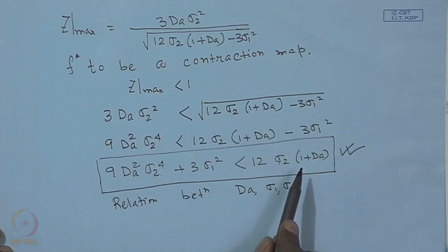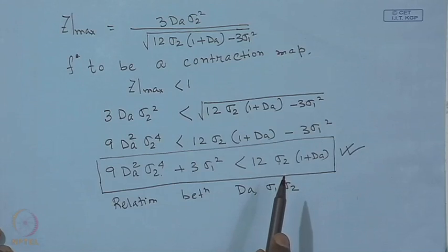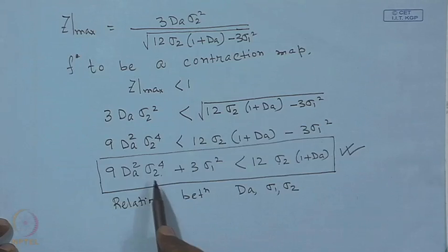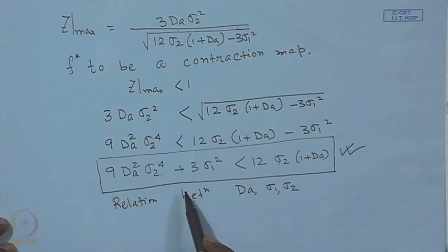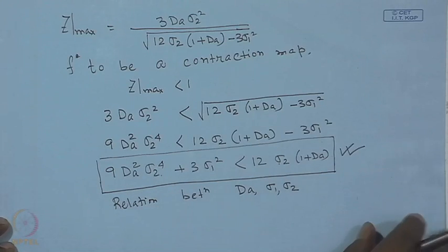So, you have to select Q and Cf, these are the actual operating conditions you are controlling as an operator. On the other hand, these kinetic parameters K1, K2 and K3 are fixed by the rate expression, you do not have much control over them. The control you have is over the feed concentration and volumetric flow rate, and these non-dimensional numbers are combinations of these. So, this equation has to be satisfied in order to get a unique steady state in your problem. Therefore, we finish the contraction mapping stuff.